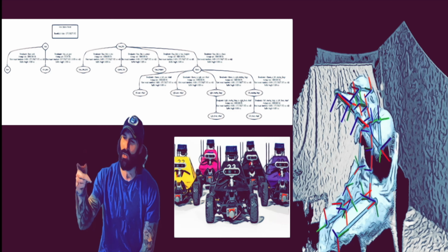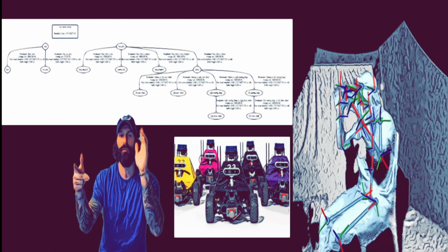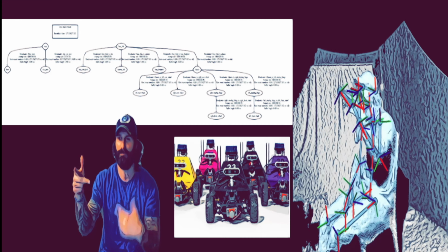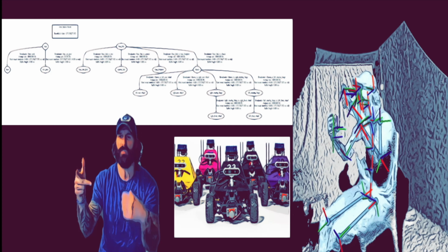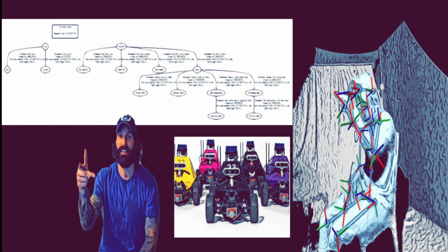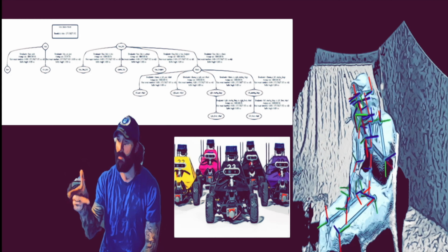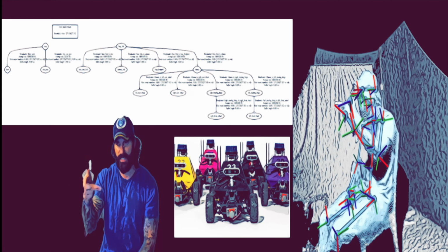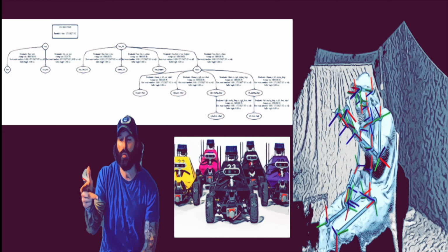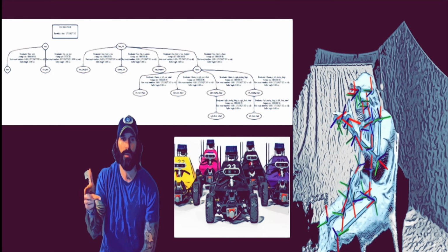If you take a look at the frames above me here, you'll actually see a view frames command pulled from ROS. That is running the race car simulation. And each individual one of these, from the SimPose and the base of the car, the camera length, the base footprint, the left wheel, the right wheel, every single one of them will have a reference point, right? So you have a Z, an X, and a Y. And these are kind of like those angles on Euler angles, each one, but in ROS, it only deals in radians and quaternions. And there's a significant difference.